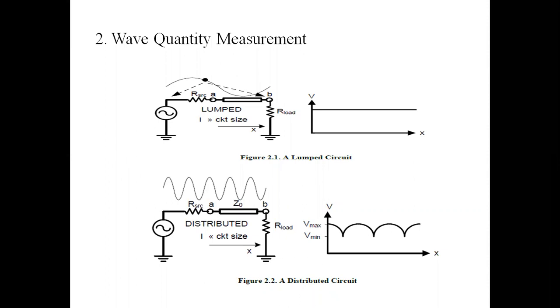For a certain voltage, that is the E field, and current, the H field, the relation is imposed by the electrical properties of the line. In fact, a cable itself behaves such that it is characterized by an inherent impedance that does not change as long as the properties of the line or cable do not change. This impedance is called the characteristic impedance, which we always denote by Z0. As the electrical power hits the termination, that is the load, the voltage to current relationship is now imposed by the impedance of the load.